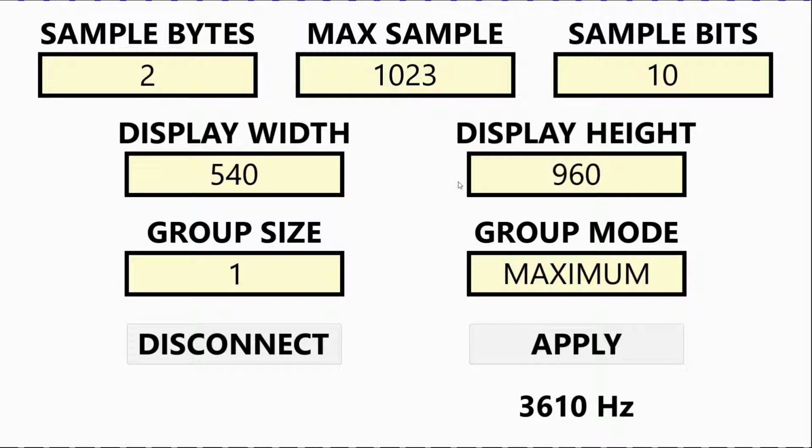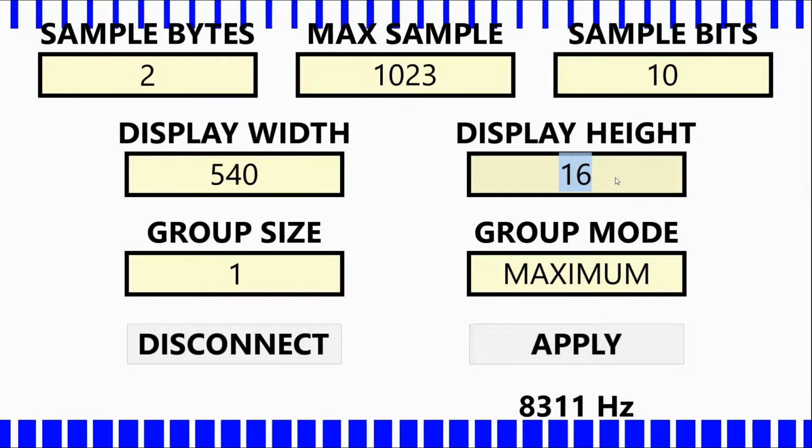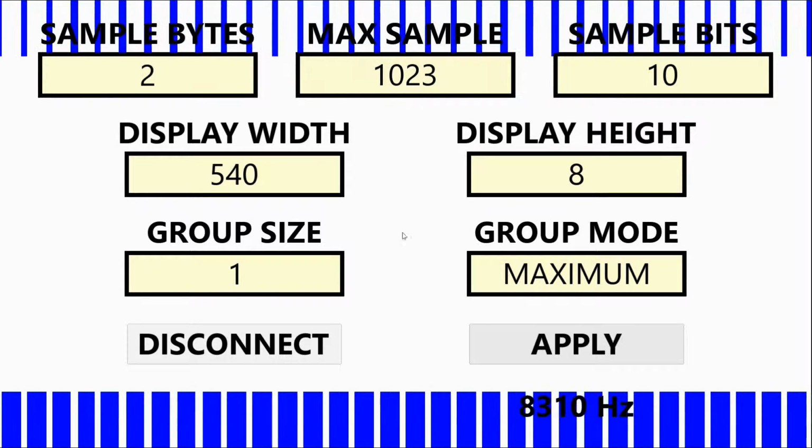So I've now plugged it in, and if you have the full resolution, you can very dimly see way up here some dots moving, way down here some dots moving, because it's alternating between maximum and minimum. Let's make it easier to see. Let's make it even easier. So now I'm taking the samples as only 8 pixels high and stretching them, because we already know it's either the top or the bottom pixel. So now you can see these at the top, this is where it's high, this is where it's 5 volts. These are smaller, and the ones at the bottom are bigger. This is where it's 0 volts. That means the bottom, it's 0 volts for more time.